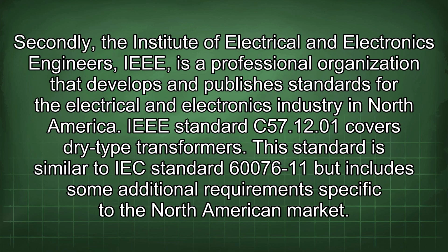Secondly, the Institute of Electrical and Electronics Engineers (IEEE) is a professional organization that develops and publishes standards for the electrical and electronics industry in North America. IEEE Standard C57.12.1 covers dry-type transformers. This standard is similar to IEC Standard 60076-11 but includes some additional requirements specific to the North American market.